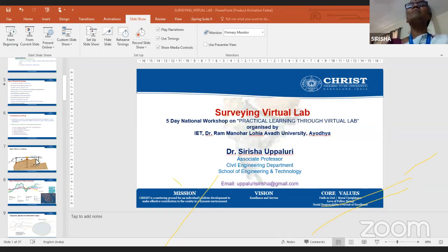On the level plane, I am going to draw a horizontal line. That is called the horizontal plane. So leveling means we are going to take the readings from the horizontal plane. We have to ensure the telescope has a horizontal line of sight.